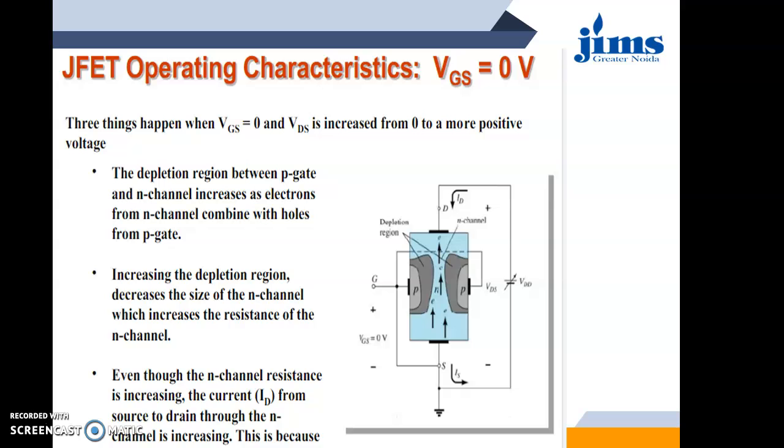It is because the upper PN junction side is reverse biased, as VDD is reverse voltage for that, and the lower PN junction side is forward biased, as VDD is forward voltage for the source terminal. In forward bias the depletion width decreases, and in reverse bias the depletion width increases. Due to this, a peculiar shape called a wedge shape is obtained in the depletion layer, as shown in the figure.